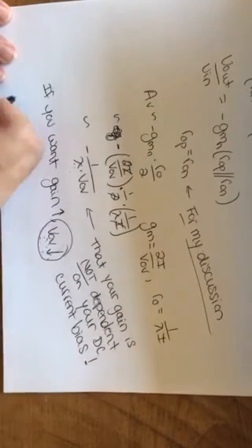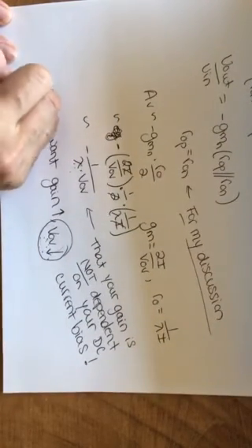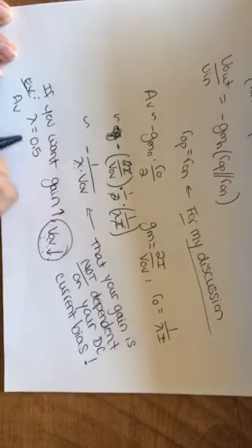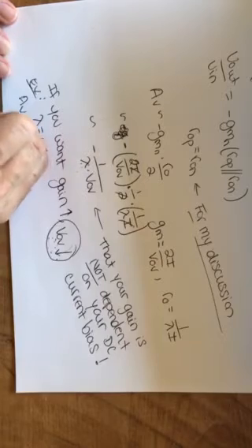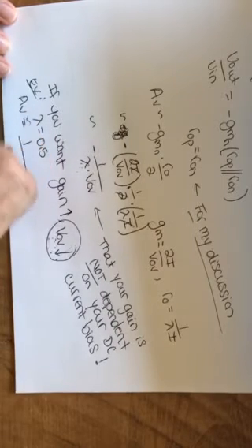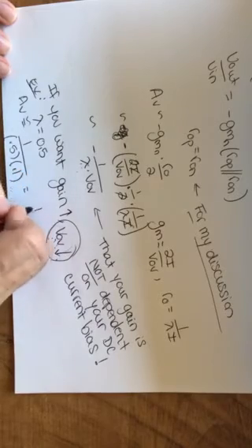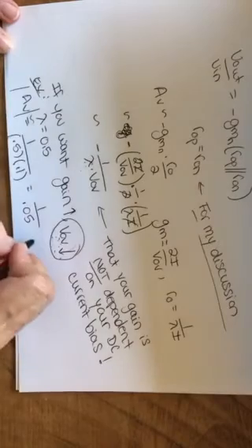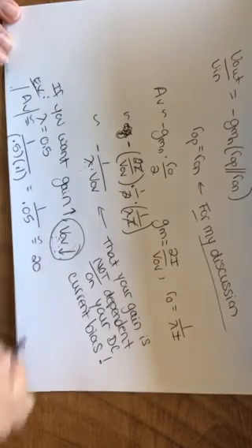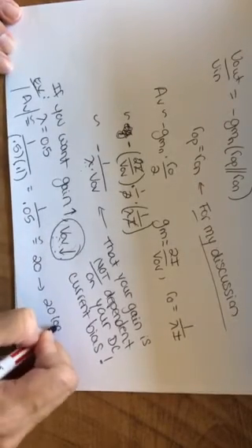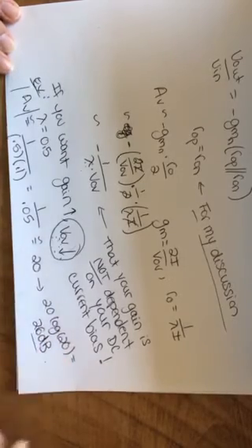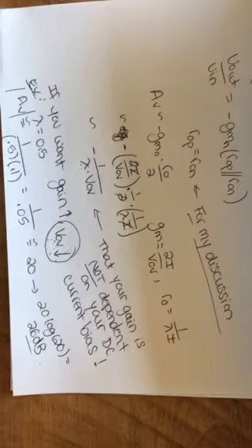All right, so for my example, I said assume my lambda was 0.5. That was my lambda. Your lambda, of course, is different. Then my small signal gain would have been 1 over 0.5 times 0.1, which is 1 over 0.05, absolute value. So it would be inverting. So I would get a gain of approximately 20. And 20 log of 20 is 26 dB, which is my spec.